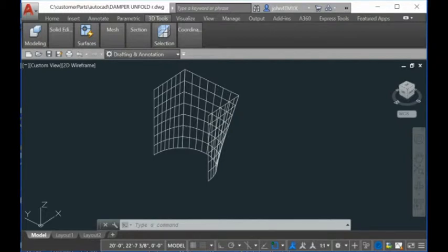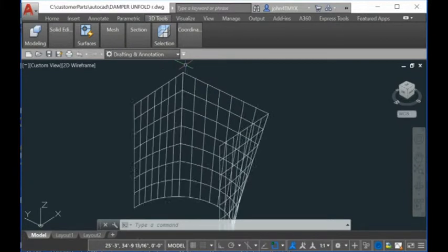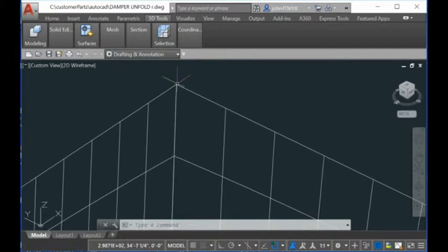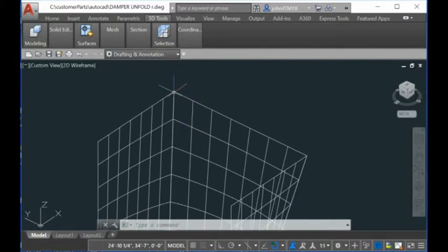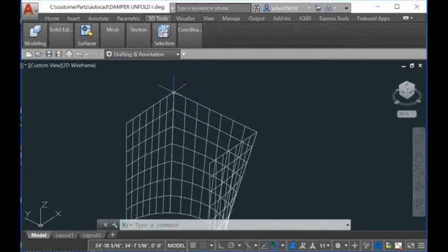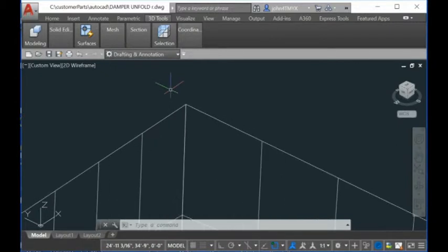If you look at this model, this surface here, you cannot manufacture it. You know why? Because there's a sharp joint here. You cannot cut it here. You have to have a fillet here in order to manufacture it, because otherwise you cannot bend it. You cannot bend the continuous material with a sharp angle here. You're gonna break it, right?